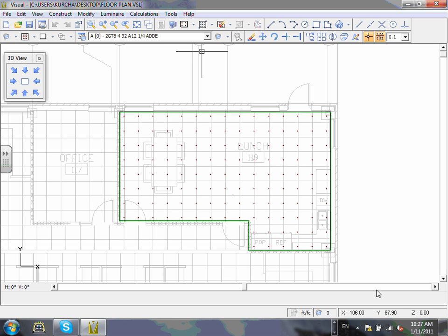To place the fixture, the first thing, Spencer, you need to know, make sure the fixture number is highlighted in this box. This means that particular fixture is ready to be placed into that ceiling. Now, I only have one fixture here, but if I have 15 fixtures, what do you think? I can scroll here between the 15 fixtures and pick the one that I want to place, right? Everybody with me? They will be all here, and I scroll to the one that I want to place, and then when I'm done here, I can go to another fixture and so forth. So all your fixtures that you load, they're going to be right in there.